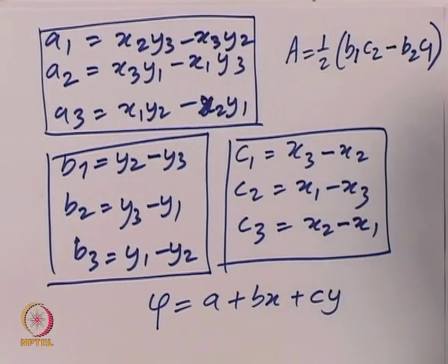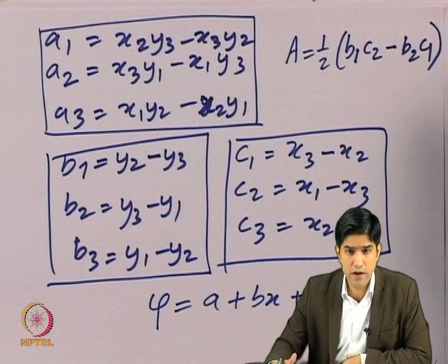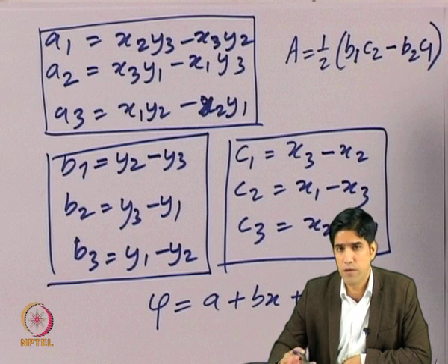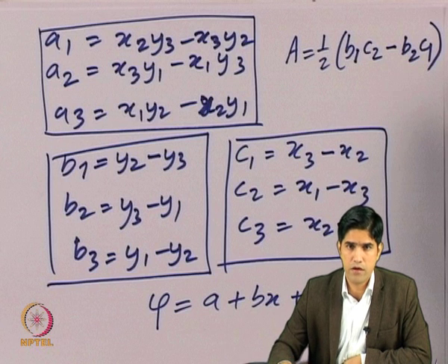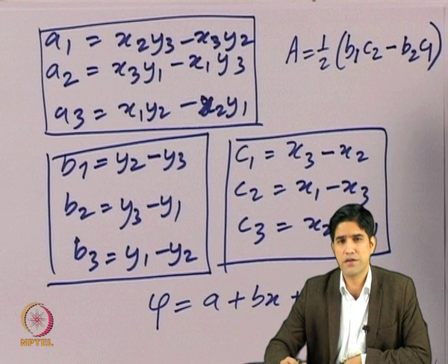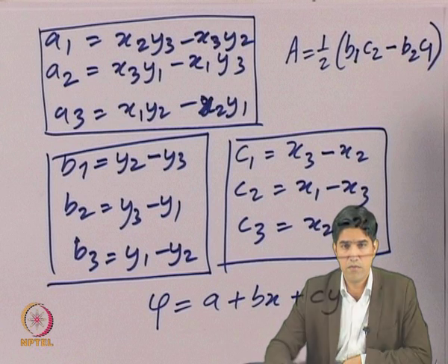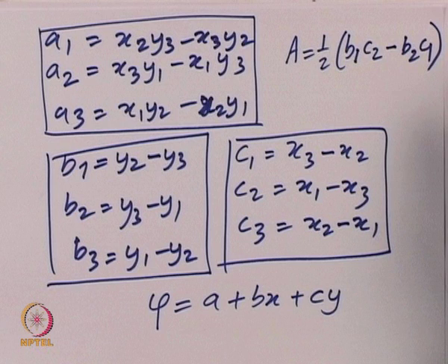So in a nutshell, what we have done is, the moment our coordinate systems are fixed, our geometry is discretized, we know the nodes, we know the elements, the value of the basis function is also fixed. If we say we are going for a linear interpolation, then we can accordingly find out what will be the value of the basis functions for each of the elements. So that way we are on safer ground. So we are going to go now one step further.